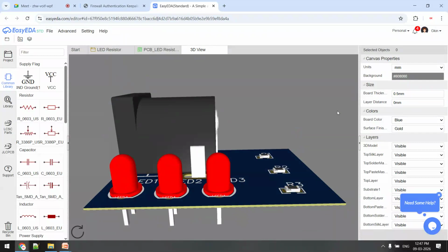More metal means one aspect is that it will occupy space, and along with occupying space it is of no use, because our purpose is not to throw it on floor just to check whether it is robust or not. We have to use it, for example in a mobile phone this PCB to be used, or in some particular military application, a very portable device, this PCB to be used. Then why increase the width? So that can be reduced. Otherwise, if we want to put some components on this part, then we can increase.